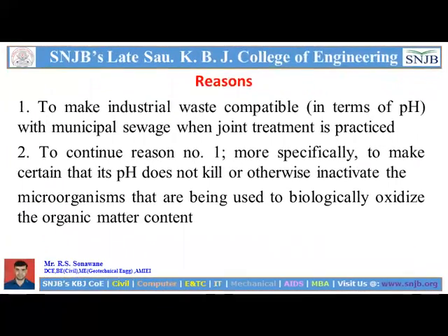So what are the reasons we can see here? To make industrial waste compatible in terms of pH with municipal sewage when joint treatment is practiced. Okay, this is the first reason. When the discharge of a particular industry is made, they always maintain pH. If pH is maintained at exactly 7, it is automatically neutralized, and then it can be disposed into the particular stream or the sewer. That is the joint treatment practice.